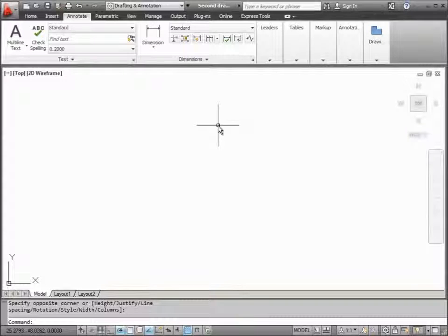When I've started a new drawing, one of the considerations is I have to set the drawing units for the object that I'm going to draw. In model space, I'm always drawing at full size, and as far as AutoCAD is concerned, a measurement unit is just a unit. How it displays those units for us is our choice. They can be displayed as inches or decimal inches or feet or meters or miles or light years. It's our choice, but we have to make that setting.